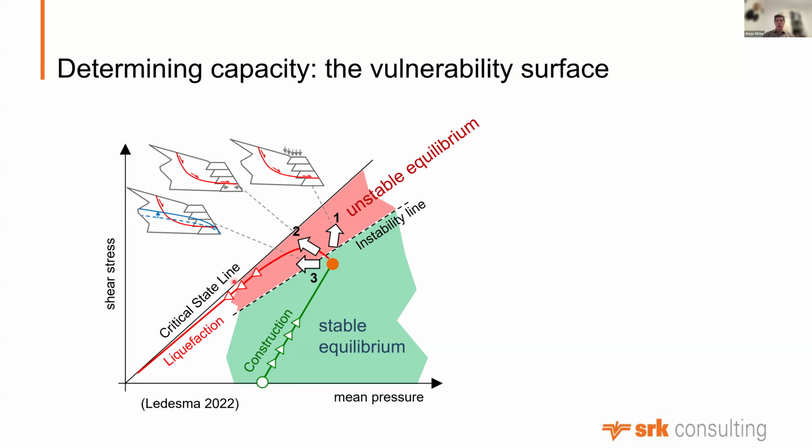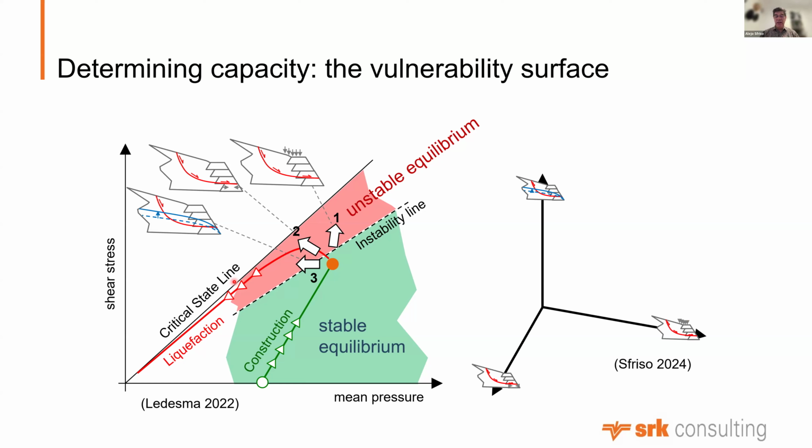Those things you do, and what you may do with those is create this kind of conceptual 3D graph, and you put the load that triggered flow liquefaction on this axis, and this dot is the load that you computed. Same for water, same for displacement.